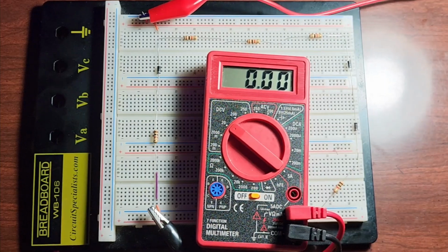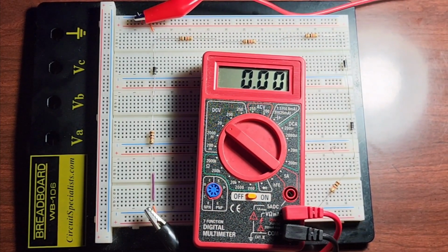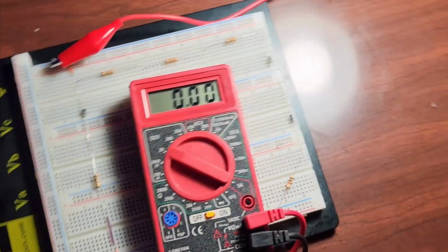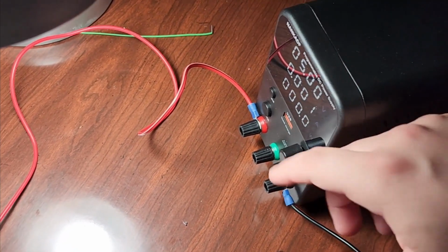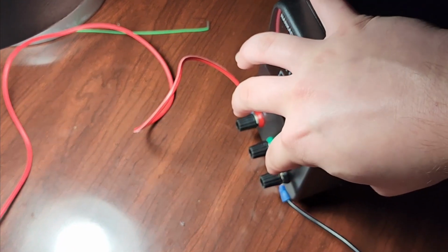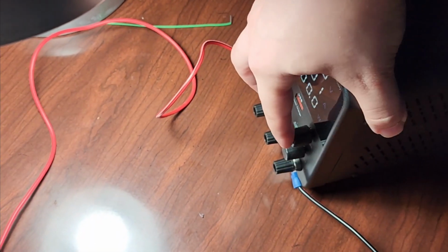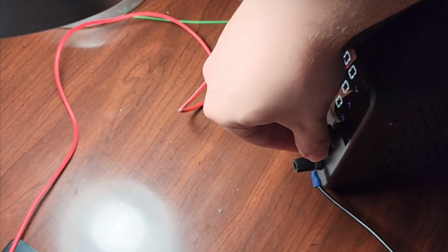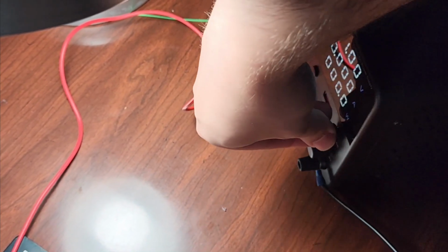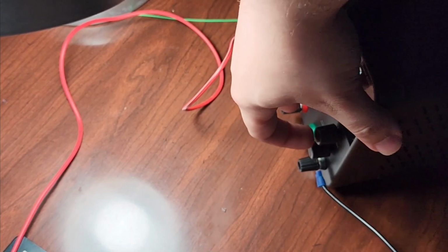And you know what we'll do is we'll change it closer to the bounds. Remember, Vn has to be at least 1.2. So we'll change our Vn to be about 1.5. Oops, don't want to see 50 volts.